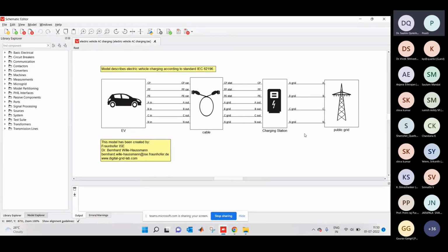For charging electric vehicles, an exchange of information between the EV supply equipment and the EV is needed, just to have defined conditions like charging power and other things like battery voltage and current. This signaling is based on the international standard, which can be distinguished in four modes: three for AC and one for DC charging. And I'll show you this in the application note.